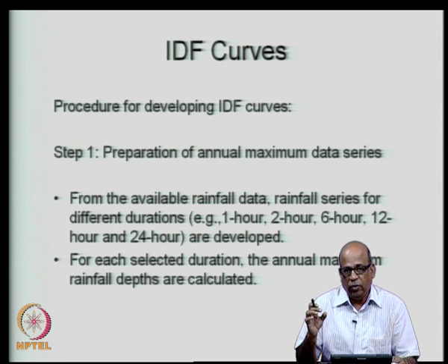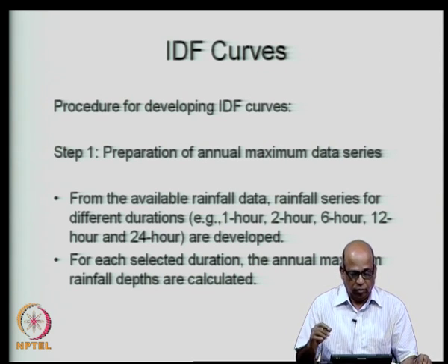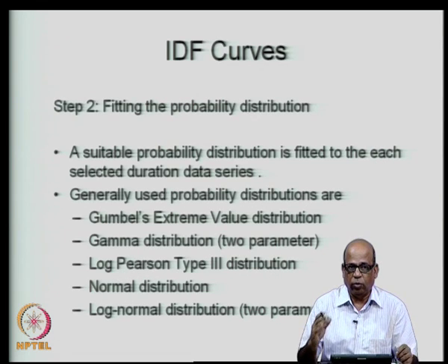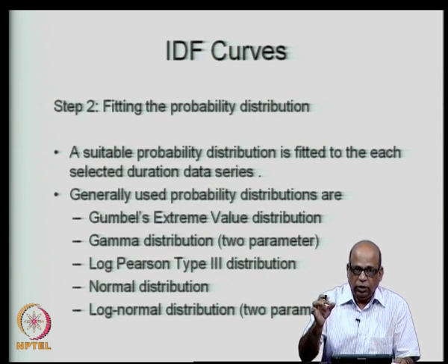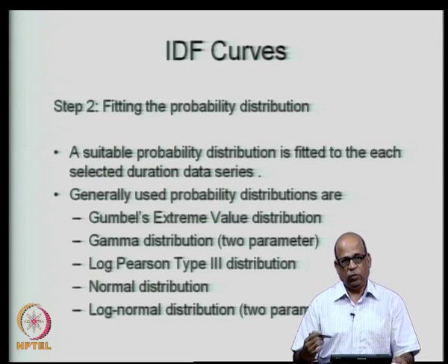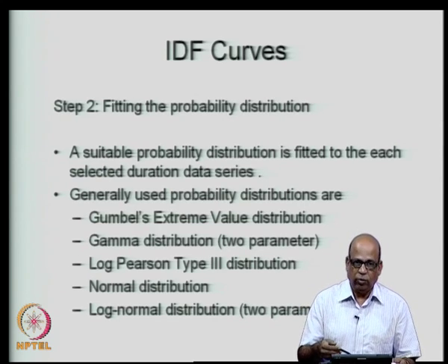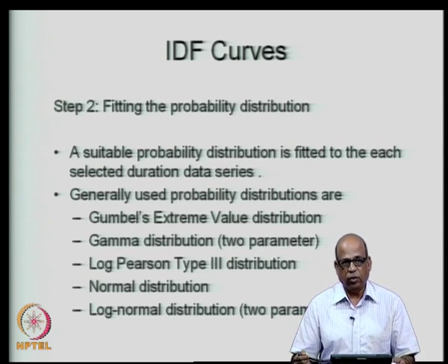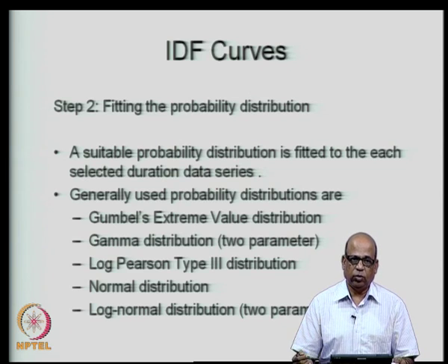Then associated with each of these series, let us say we fix our attention on one of the durations, 1 hour duration or 2 hours duration etcetera. For each of these selected durations, we fit a probability distribution. When we are dealing with extreme rainfall values, typically we use the extreme value distributions. However, it is not uncommon to see applications of normal and log normal distributions also.